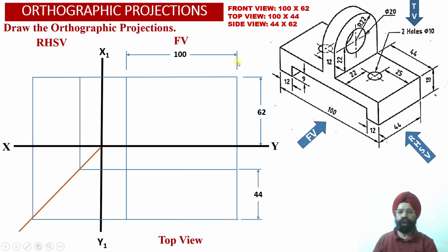So here from the right hand side face of the solid, we are going to mark the center point corresponding to this hole number 1 into this horizontal element over here. Now we have measured a distance of 25 millimeter from the right hand side face of the solid and a vertical center projector line we have been able to obtain into the front view projections, and we have extended this center projection line into the top view projections over here.